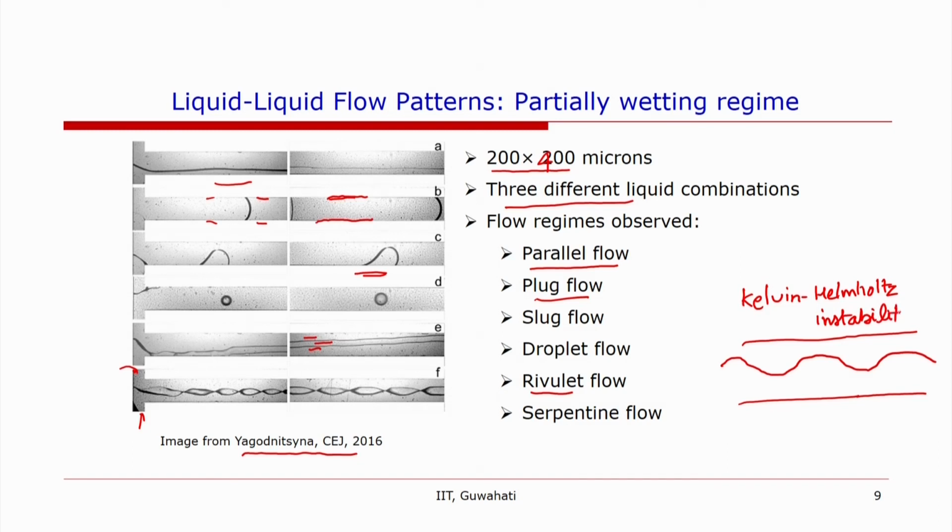So Kelvin-Helmholtz instability is generally seen when there are two different fluid streams with different velocities, u1 and u2. Originally, it was derived for two fluid streams which are flowing parallelly and the two streams are inviscid. When the fluid streams are inviscid, there is no velocity profile in the two, and then Miles looked at the effect of the velocity profiles on the instability.